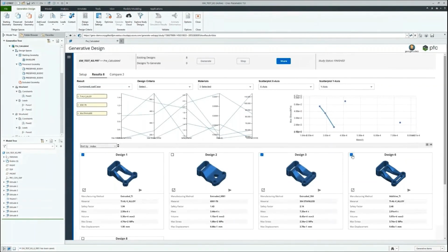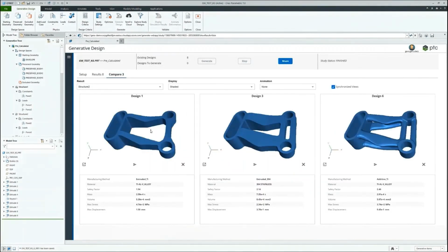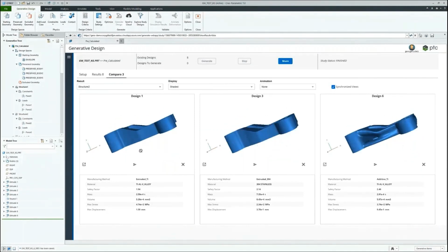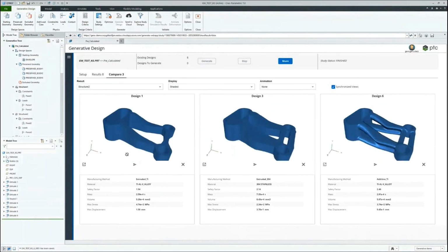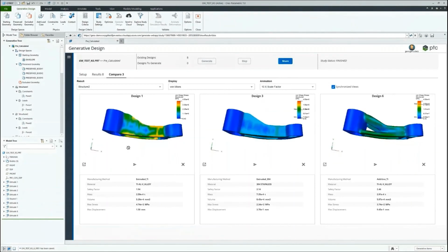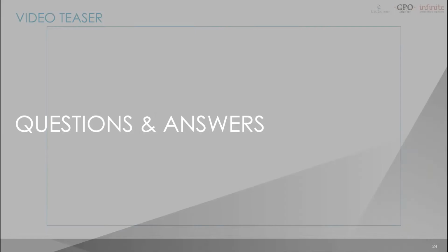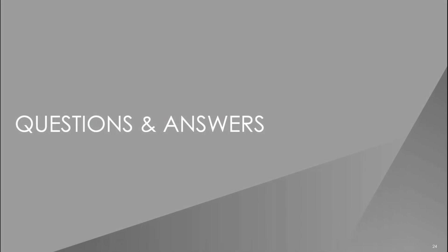From there, a sub-selection has been made of, say, 3 designs, fine-tuning which design is optimal for you, and the structural integrity of these few components is being looked at. So you can see at the bottom what material, what safety factor, the mass, the volume, the stresses, the displacement, as well as a fringe plot to see how the model will behave. When this is done, you can just output the model back into Creo and then produce your B-rep geometry. That concludes the demonstration part.